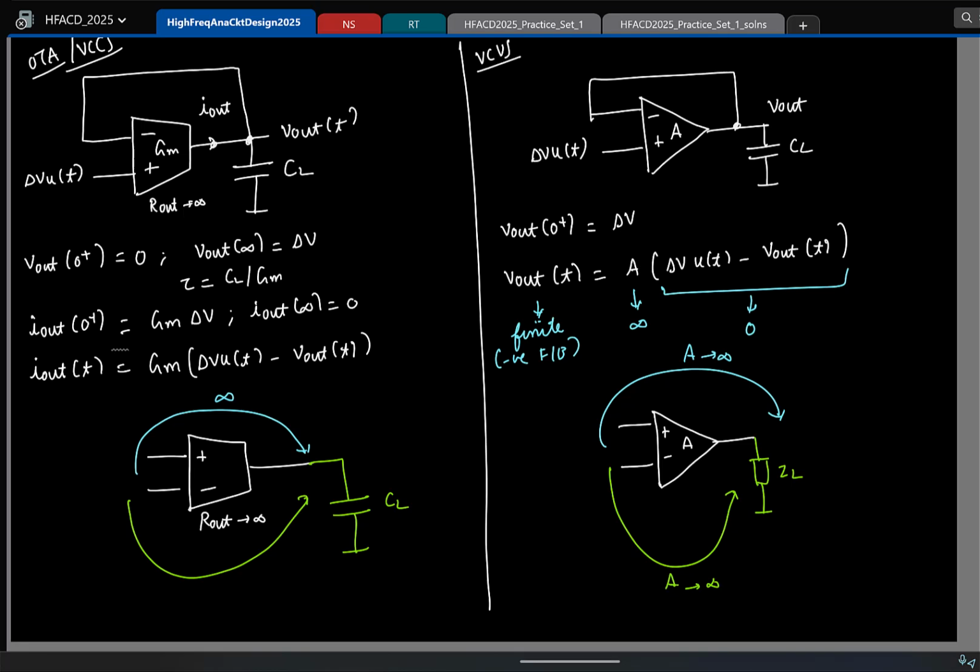Okay. So see, this is a VCCS. So what is fixed by this VCCS? The current here is fixed irrespective of what you have. But what is the voltage finally? The voltage here is the current times the impedance here, right? So voltage gain will depend on what load you have. Is that clear? This is one reason why we said we don't want to use our OTA with a resistive load. Correct? So if I have a capacitor, what can you say about the gain at DC?